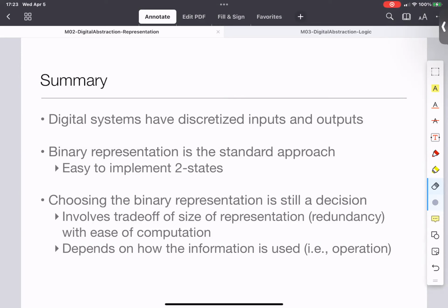In general, you can't. So the trick is in electrical circuits, we put an analog filter to remove the signals above what I am designing for. So I may say, the signal I will assume has no more than 100 hertz, let's say. And then I will put an analog filter to remove anything above 100 hertz. And that will come from experience or prior knowledge about your signals. These filters are called anti-aliasing filters precisely for this reason. They're designed to just get rid of signals above. Okay. Thank you.